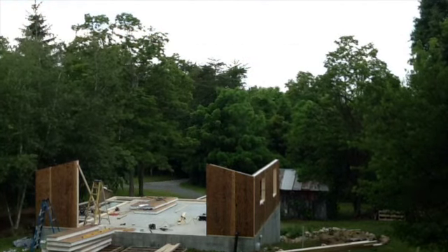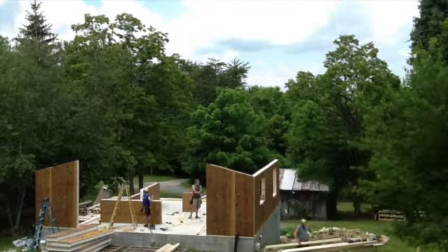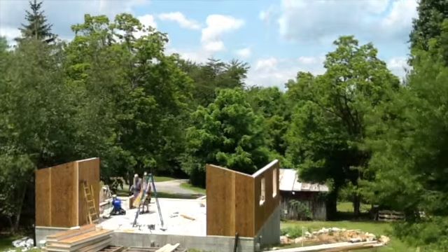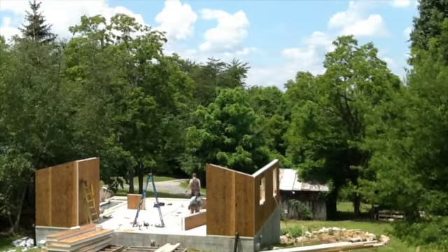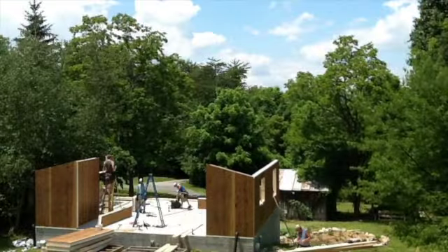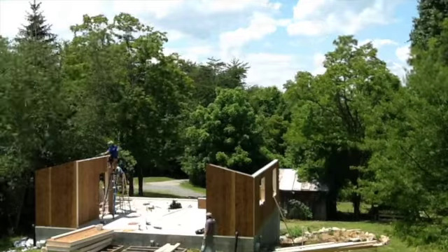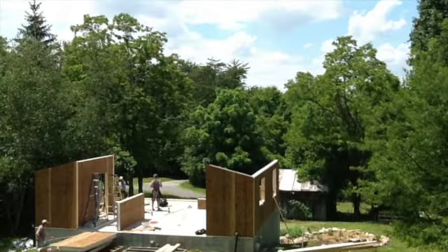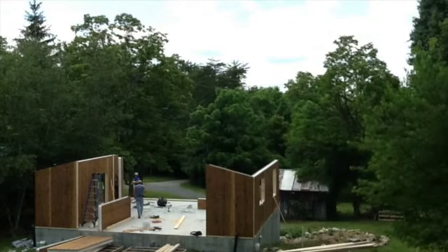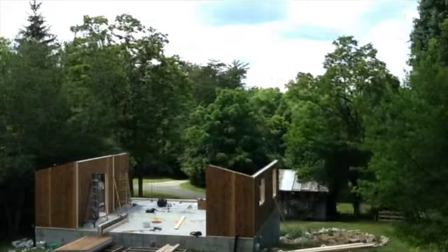You'll also notice that they are building a wing along that wall to support the roof, but the area of the elevator shaft and the stairwell are not within the conditioned envelope of the building. So the area outside there was built with stick framing since it was not meant to be conditioned space, and that actually saves some money on the project. That's why that wall on the left-hand side of the screen is set back from the edge of the building.